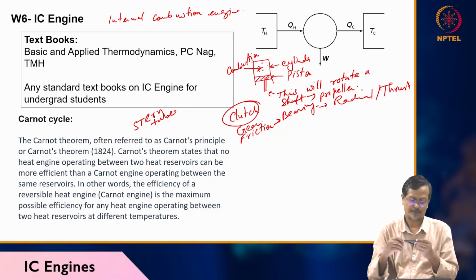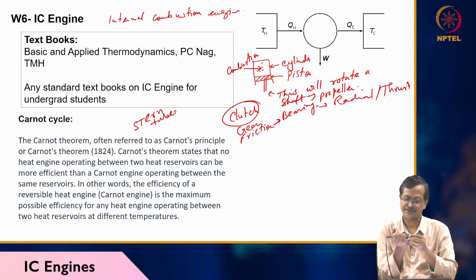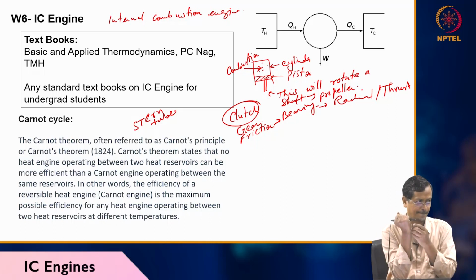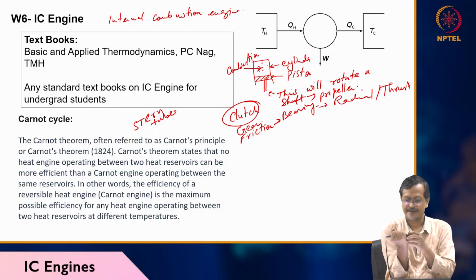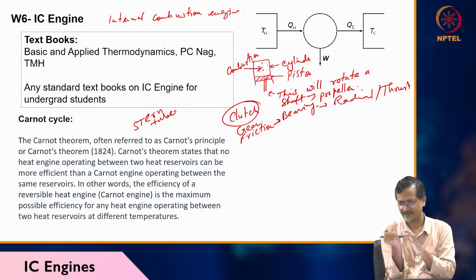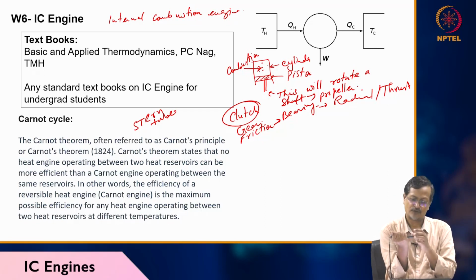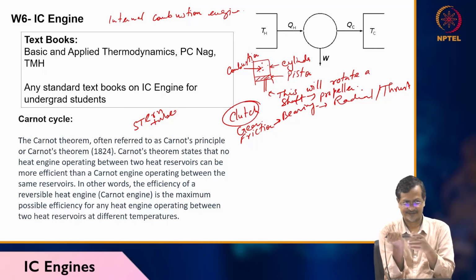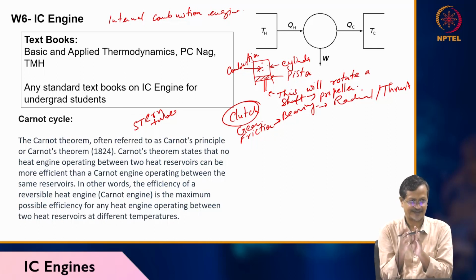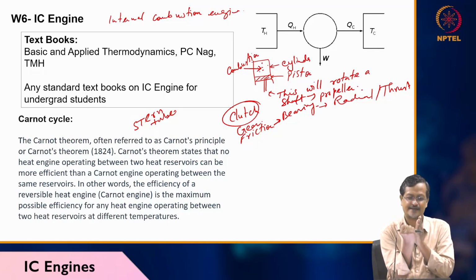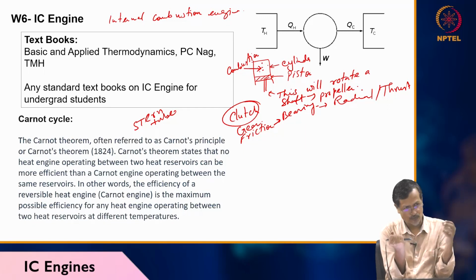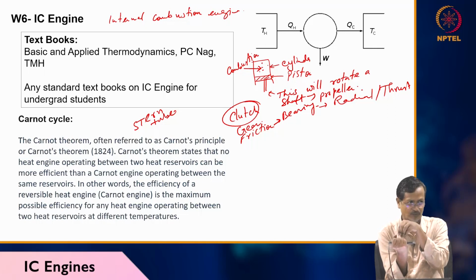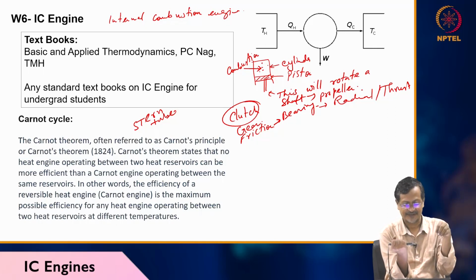Now when the propeller is rotating, the propeller shaft will be passing through one bearing. The bearing must be lubricated to reduce friction. Now when the propeller is rotating, water splash will go into this lubrication section. When it goes into the lubrication section, the lubrication will be washed away by seawater. Then you have to seal properly on both sides. Like I say, this is my bearing holding, and I seal this end and this end. So the sealing must be proper. The sealing will not allow water to enter, or the grease or lubricant inside to go out. So this is called stern tube sealing.